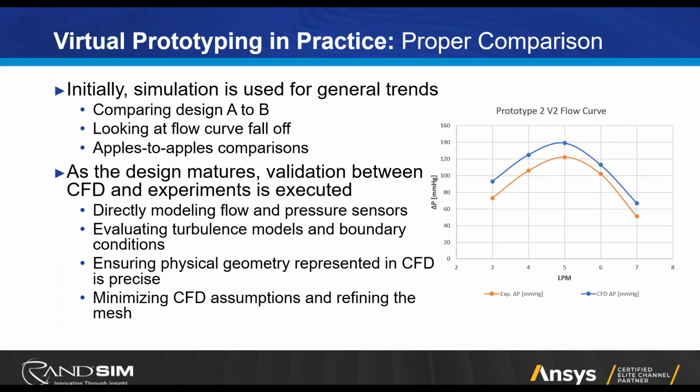And so this validation isn't adding artificial tweaks to the CFD model or anything like that. It's just making sure that our CFD model and our experimental setup really are showing the same exact picture. We're doing pressure measurements at the same exact site. We're actually modeling in some of our measurement tools in the CFD analysis.